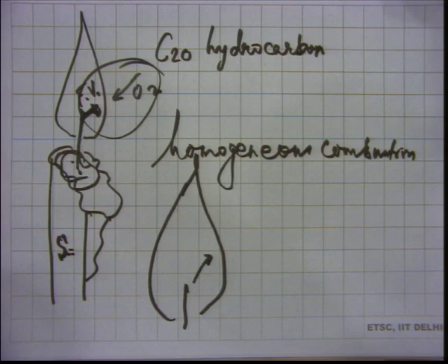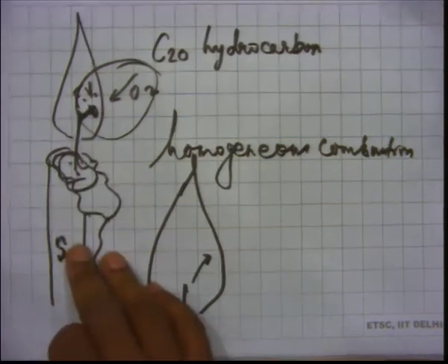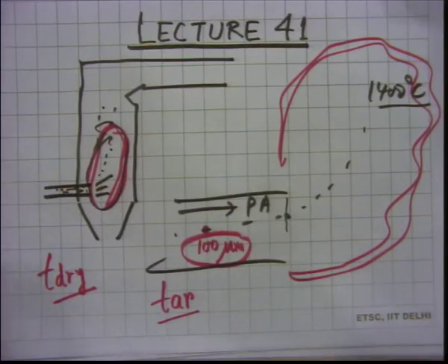Those are not directly there in the fuel, whereas in the boiler situation that we were talking about, the particles were there. You took the coal, you pulverized it. There are ball mills, okay? There are pulverizers in power plants where you break the coal particles into this micron size, 70 micron, 100 micron, 120 micron, whatever, and then you are sending them. And those coal particles have lost other things to become more like carbon. Okay, so that is the difference. They didn't get produced in the flame zone.